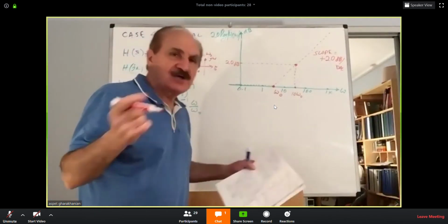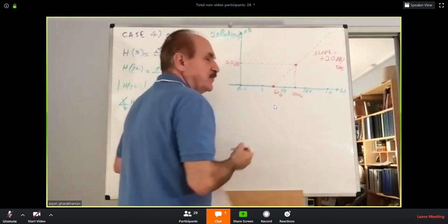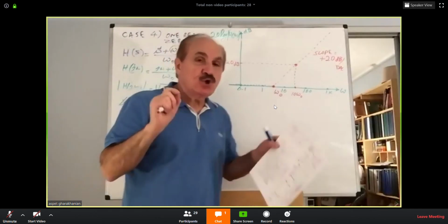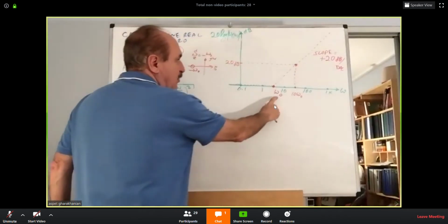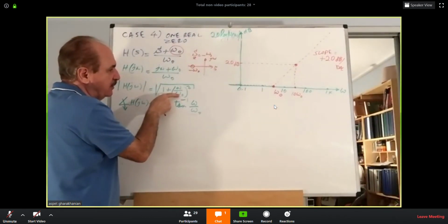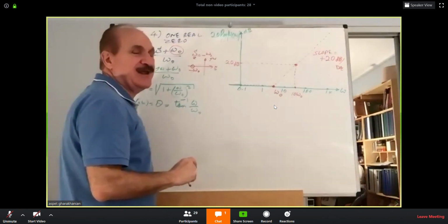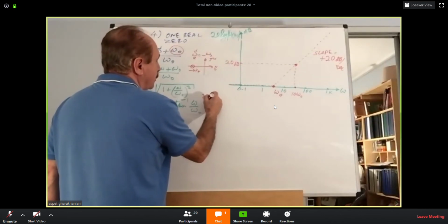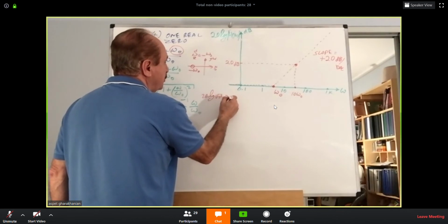Now, correction. How do you correct the smooth curve? There is one point of that curve that we are sure it's going to pass, and that is the value of omega O. Check here. If you make omega equal to omega O, this will be 1. So under the radical, you will get radical 2. 20 log of radical 2 is just 3 dB.